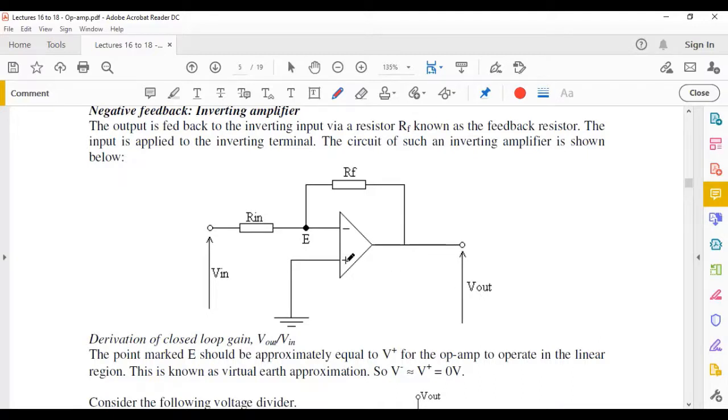Now, like I've said earlier, in this symbol here, you still have these two supply terminals. Be careful, they're still there, but we typically don't show them on all circuits. Okay. Now, let's see how this behaves. For us to have stability, it means this terminal you find there at the inverting terminal should be the same as this terminal. If you have any difference, the negative feedback that you're applying would ensure that these two terminals are at the same potential.